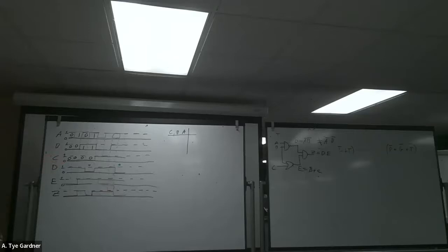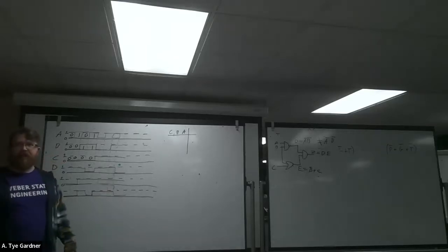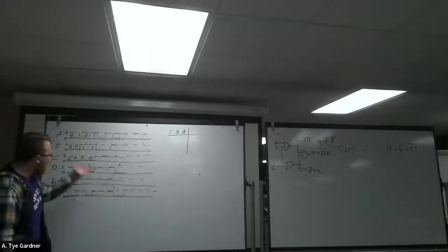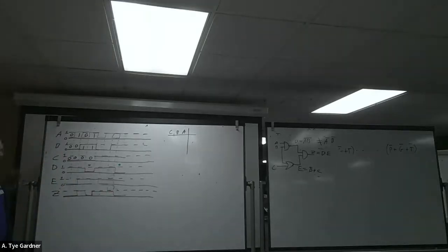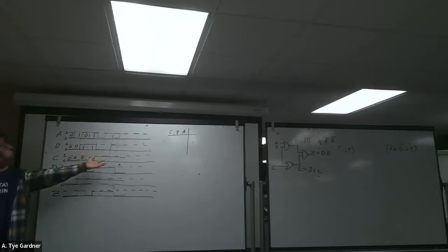Because what happens is when I need to test something, right? If I'm going to test, that's what this is doing. I'm just testing. Does the circuit do what I want? You're going to tell the computer what the inputs do, and it's going to tell you what happens to the outputs. And it's going to create a diagram that's a timing diagram, and you're going to see if it makes sense, if it's doing what it's supposed to. This is why timing diagrams are ultimately important, but it also gives us an interesting way to talk about the circuits changing through time.